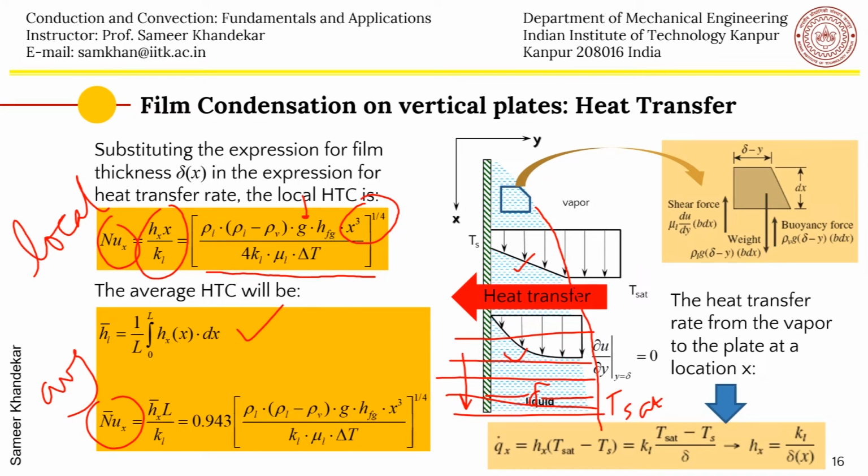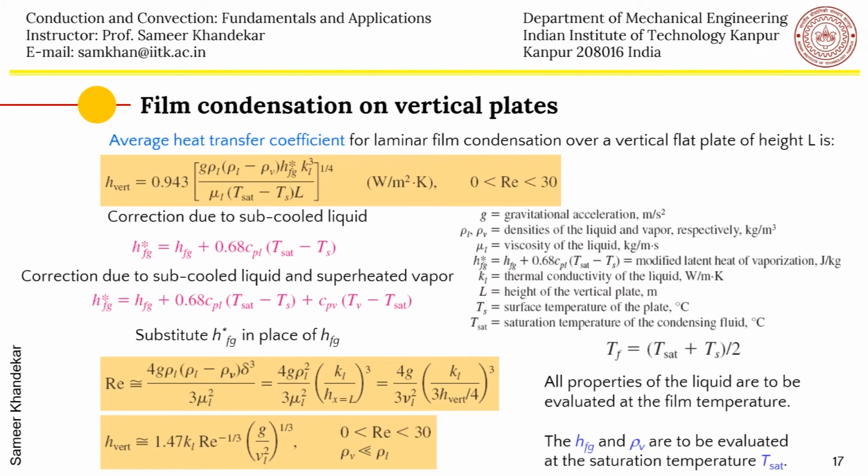Now, of course, as we have noted down, the vapor temperature may not be at saturation, so it may be a little bit higher than saturation. So some amount of sensible cooling of the vapor will also take place, and therefore a small correction may be needed.